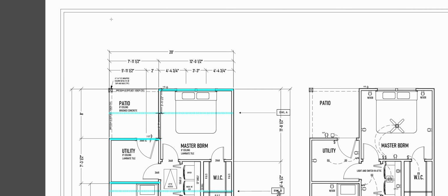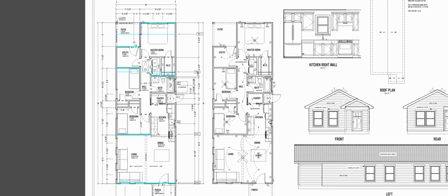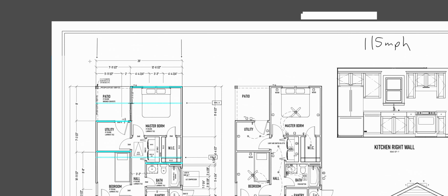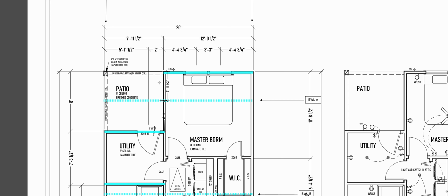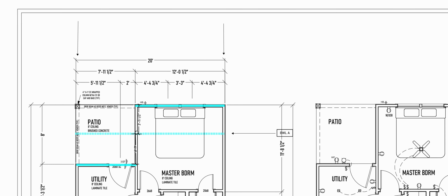I could design with this wall here and basically ignore this little piece, and I know I'd have tons of design strength and everything. But this will be a brace wall line, but it's going to be an uncalculated brace wall line. It's just going to be panels on it.